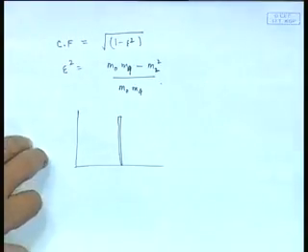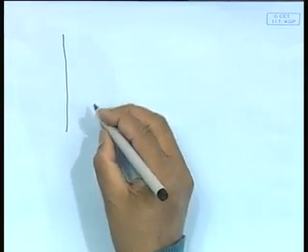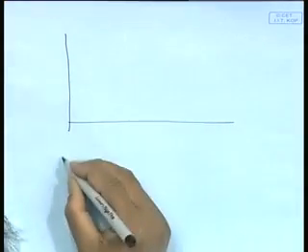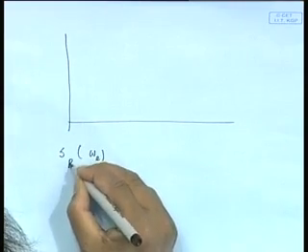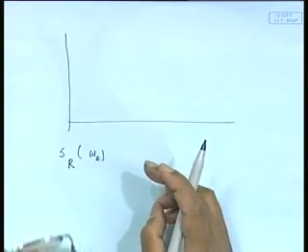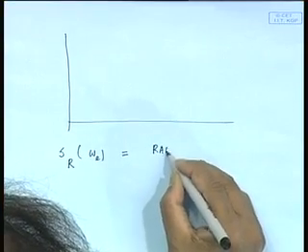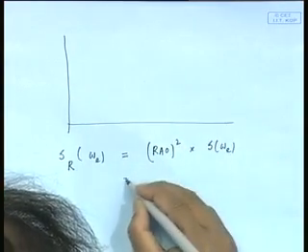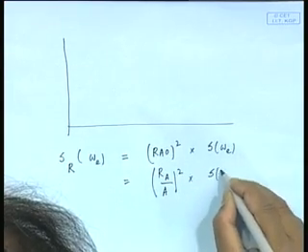Okay. See, now I want to look at some of these units, just so that we do not have any confusion on the units. See here, this side is what? This side, let us look at this again. Now let me call this a response, any response. Let me now generalize it. Instead of Z, let me call it R representing any response. So, that is going to be RAO for the response of that response square into S omega E, or I am going to call this response amplitude by wave amplitude square into S omega E.